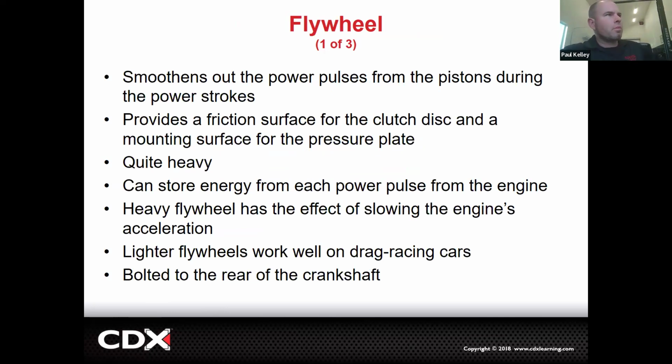Smoothens the power pulses from the pistons during the power strokes. Remember, you've got a 4-cylinder, you've got a 6, you've got a V8, whatever. There's going to be pulses, right? When cylinder 1 hits, pulse, then nothing. Then cylinder 2, pulse, then nothing. Then cylinder 3, pulse, then nothing. The firing order is probably not 1, 2, 3, 4, but it is on a couple of 4 cylinders. So bang, bang, bang. It's going to smooth those out because it has a bunch of weight.